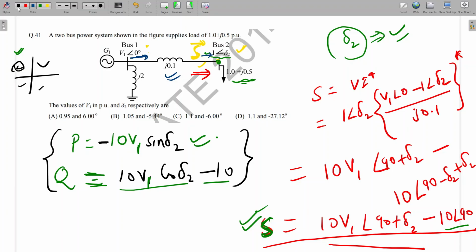But in the case of reactive power, at this node and this node will be different. Why different? Because at the middle a reactive element is there. If R plus jX will be there, in that case we cannot say that this real power and this real power will be the same, because some real power will be consumed by the resistance also. If the shunt has some resistive part, then it won't be possible. Then the real power here and the real power here will be different.